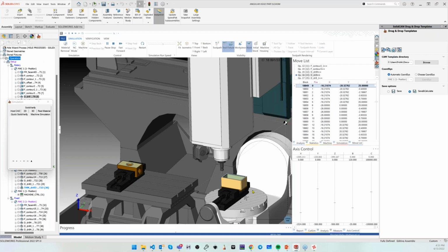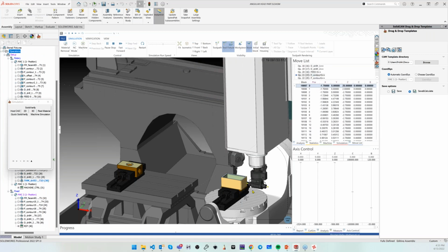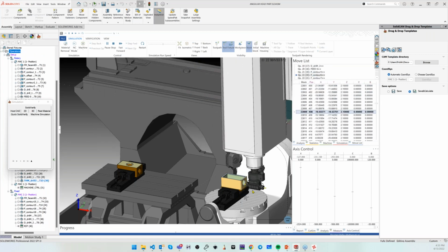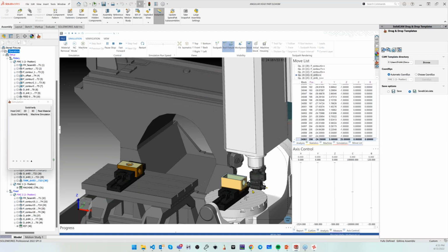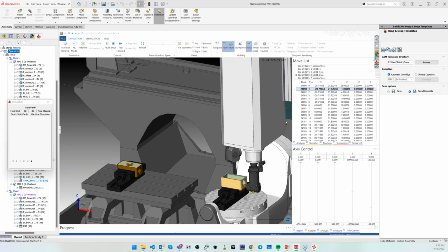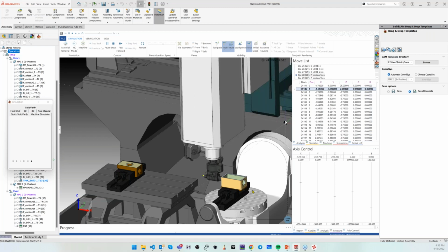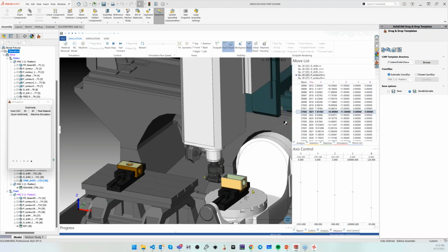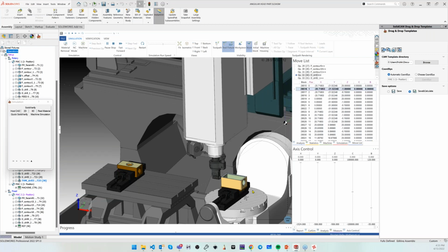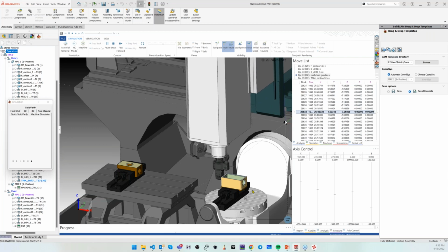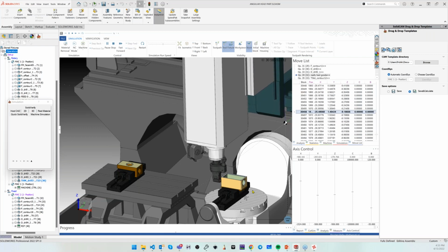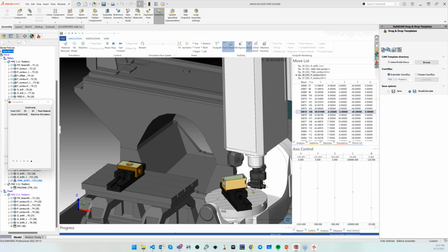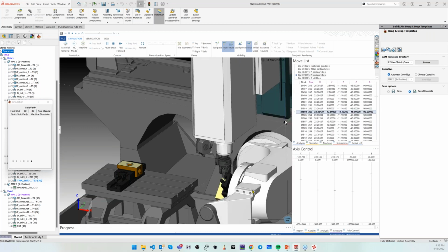You can estimate, for example, that in this part I saved 5 tool changes just by managing the proper execution of the operations. Each of these tool changes on the machine takes 5 to 7 seconds. So without changing the technology, I saved 1 minute on each part. It's a very powerful tool, and it generally doesn't require special knowledge from a customer to manage it. I will show you how to do it.